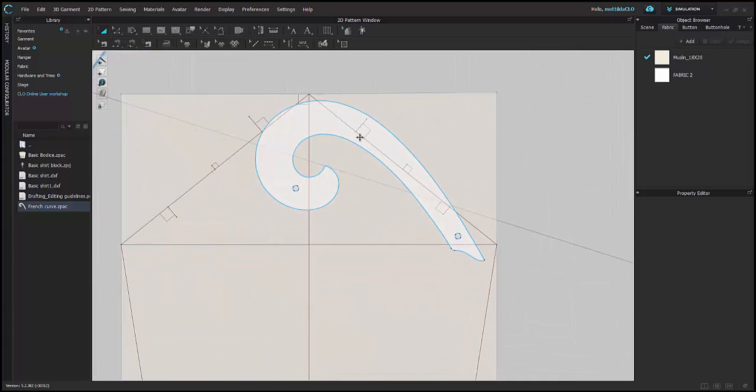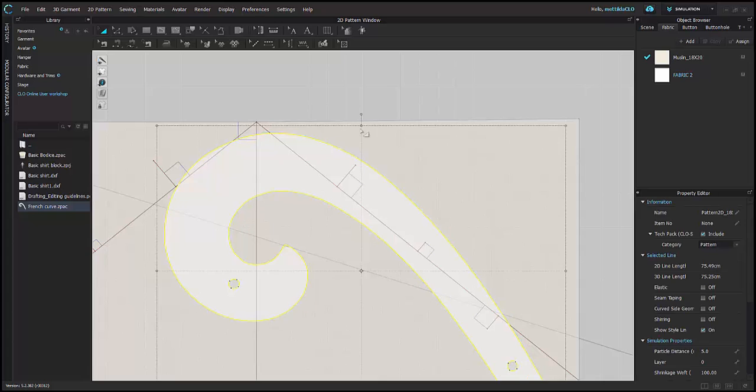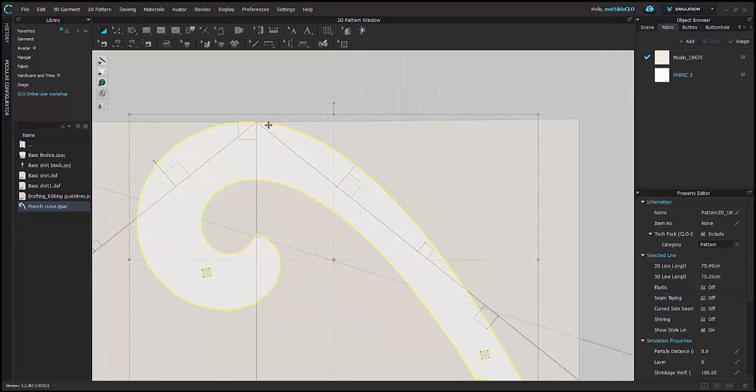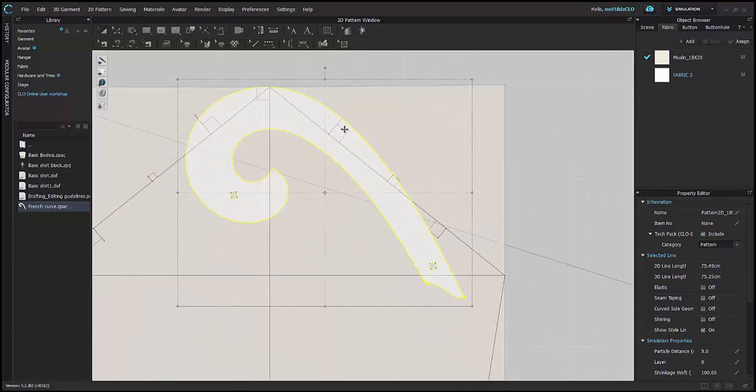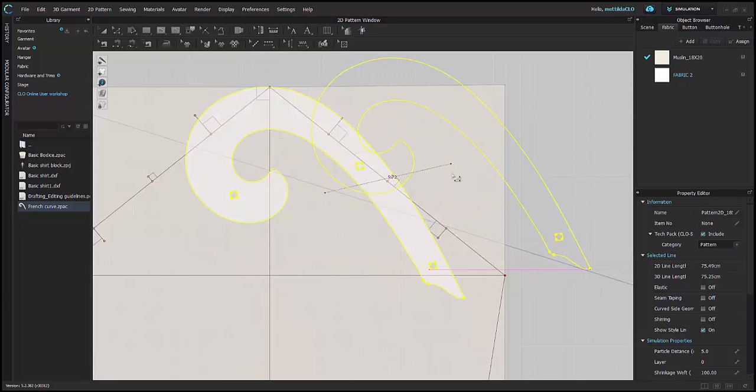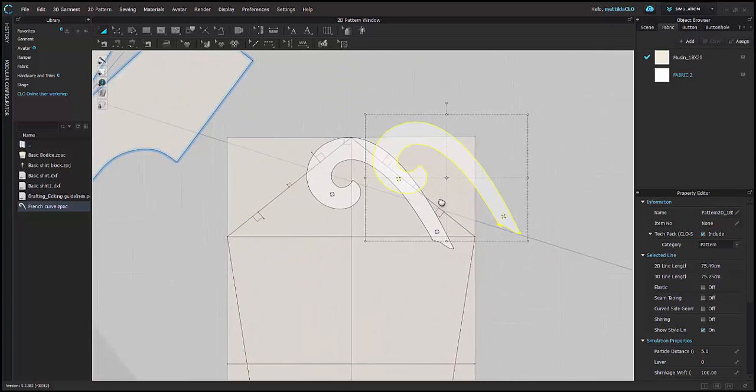Now we can place the French curve to match the first 3 points. Rotate with the small circle on the top. You can now create a copy of the French curve and flip it horizontally and vertically, then match the other 3 points to complete the curve.